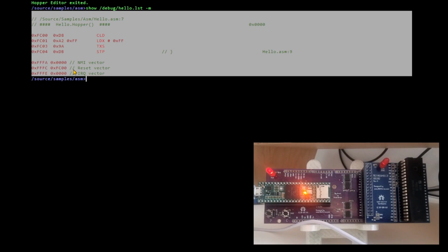These are the interrupt vectors and the reset vector, and as we suspected, our 1K ROM starts at hex FC00. What does it do? It doesn't assume that the CPU is not in decimal mode, so it takes it out of BCD mode and puts it into regular mode. It's loading FF into X and then putting that into the stack pointer, so it's initializing the stack to a reasonable known location. You don't really have to do that since the stack is circular on page 1 anyway, but it makes it easier when you're in the debugger to see what's going on.